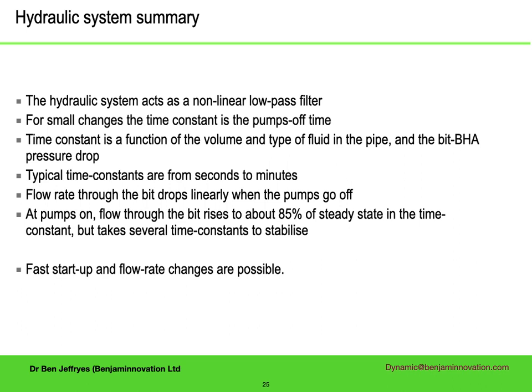When the pumps go off, the bit flow rate drops near linearly. That is why it takes time for the surface pressure to drop. At pumps on, it takes much longer for the bit flow rate to stabilize. This 85% of flow is the 75% of the pressure rise rule I told you about, converted to flow. Finally, improved startups and flow rate changes are possible through applying this theory.